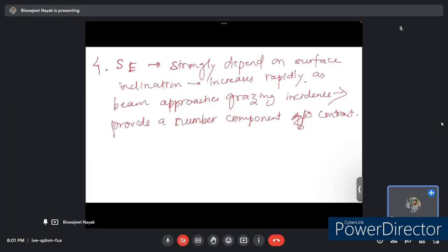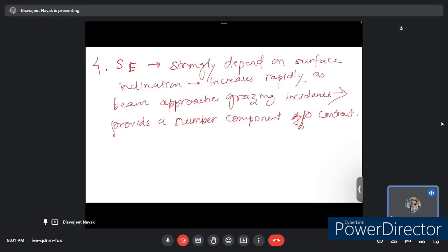So while imaging with this Everhart-Thornley detector, a finely focused electron beam passes sequentially through a series of locations on the specimen, and a mixture of backscattered and secondary electron signals is emitted, and these different types of shapes and shades provide different contrast to the specimen surface.